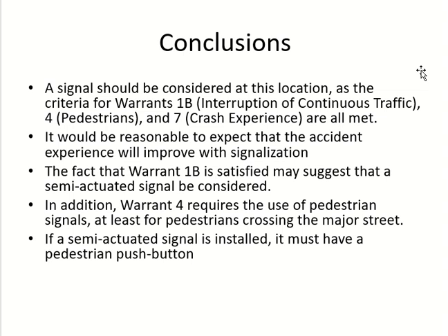Put a sensor on the minor street. Okay, sensor will do what? Because the minor volume is very, very low compared to the major, so the sensor will only open the minor road when it is required, because both of them are not high. This one is very high and this one is very low. Okay, so our sensor will make sure that the signal does not become red unnecessarily. Clear? So this is their recommendation.